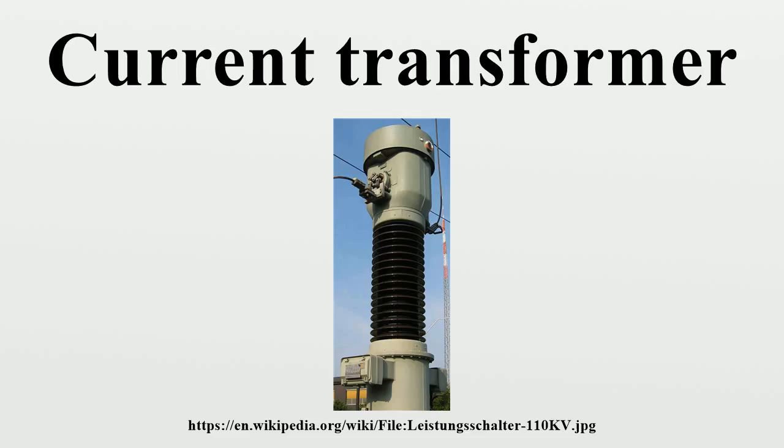Ultimately, depending on client requirements, there are two main standards to which current transformers are designed: IEC 61869-1 and IEEE C57.13, although the Canadian and Australian standards are also recognized. High voltage types. Current transformers are used for protection, measurement and control in high-voltage electrical substations and the electrical grid.